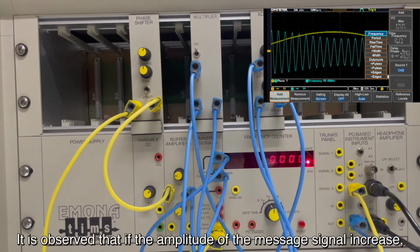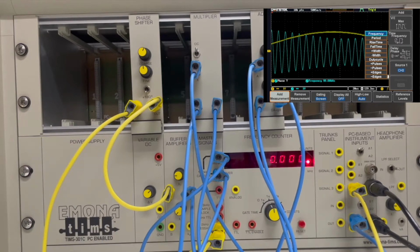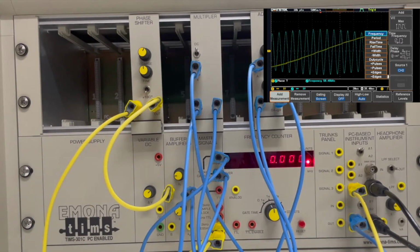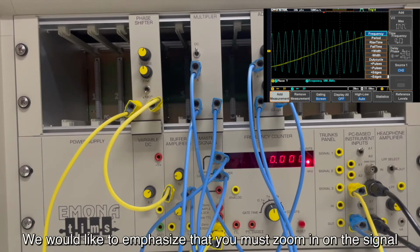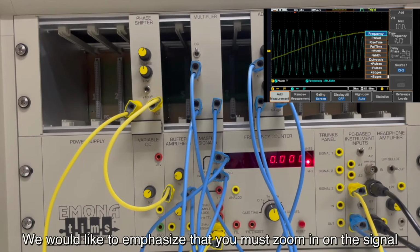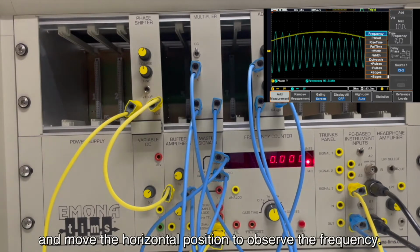It is observed that if the amplitude of the message signal increases, the frequency of the output signal decreases. We would like to emphasize that we must zoom in on the signal and move the horizontal position to observe the frequency.